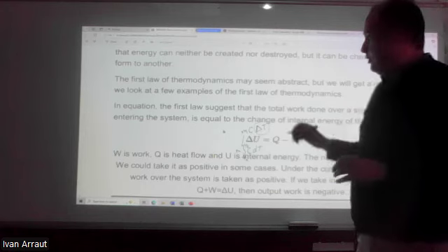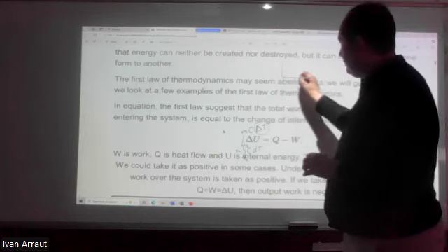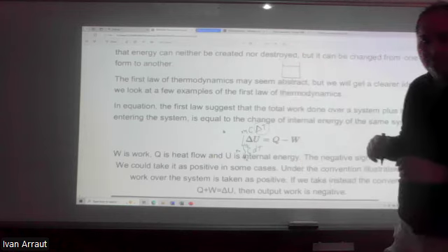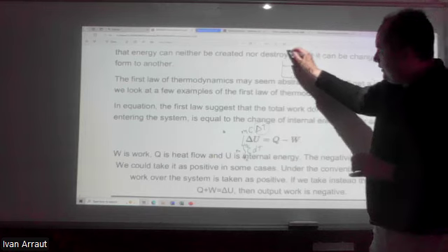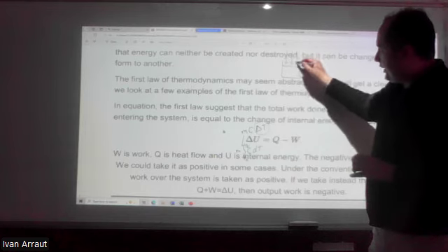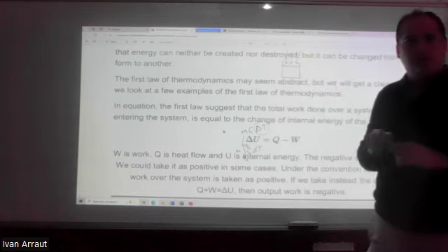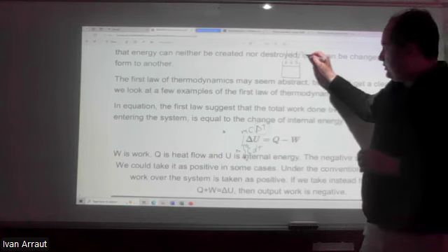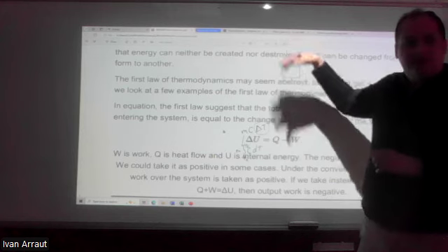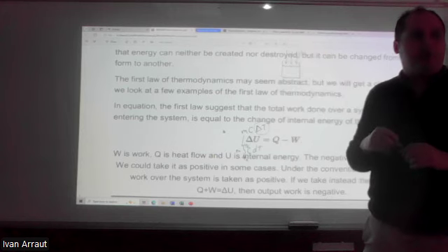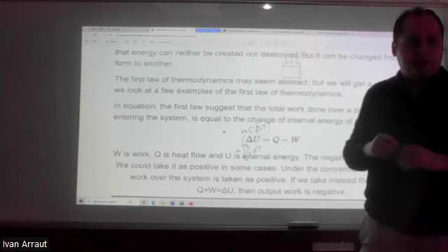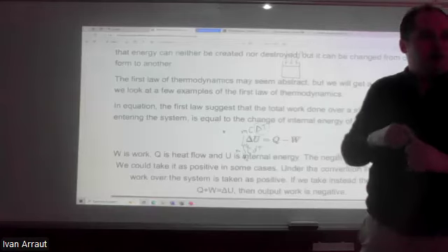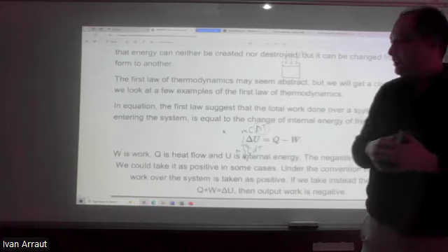Let's put it this way. I will put a tank here. Water is here. The tank is open. The air executes a pressure against the water here. So it means when I decrease this pressure, the water escapes easier and will evaporate easier at a lower temperature. So if you put in a mountain, it will be easier to evaporate, no?